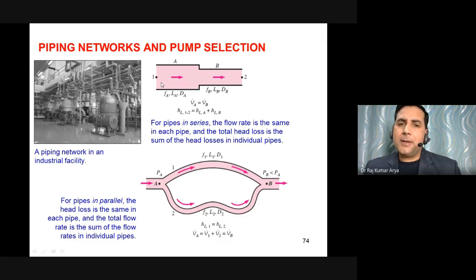So this pipe would also give some loss. This pipe would also give some loss due to the length of the pipe or the material of the pipe. Now here you have a fitting, because by means of that you are connecting the two pipes, either by welding, by flange, or by a reducer, right? So you can have so many combinations of choices here, or by a union you can connect here. Now you will have an inlet loss here.